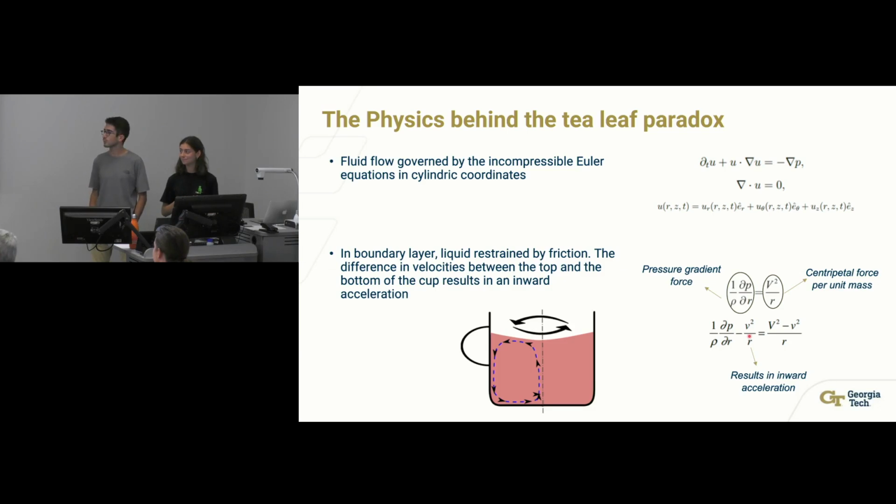Yeah, the first equation is a force balance, right? Yep, across the streamline. So Bernoulli's equation is along the streamline. If you go across streamlines, you have the pressure gradient balancing this centrifugal force. The fluid wants to keep on going, and the pressure keeps it. So it's low pressure in the center, high pressure on the outside, and that gives the top black arrows.